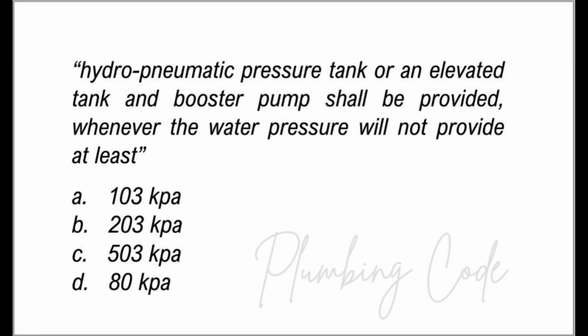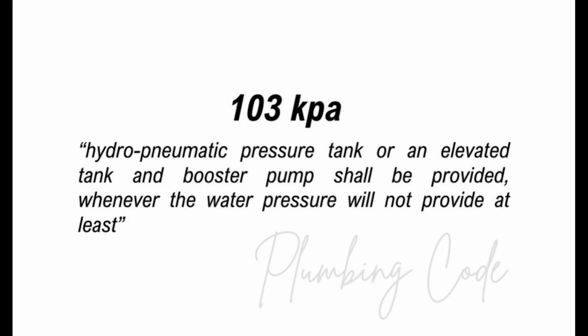Hydropneumatic pressure tank or an elevated tank and booster pump shall be provided whenever the water pressure will not provide at least how many kPa? 103 kilopascals. 203 kilopascals. 503 kilopascals. 80 kilopascals. The answer? 103 kilopascals.